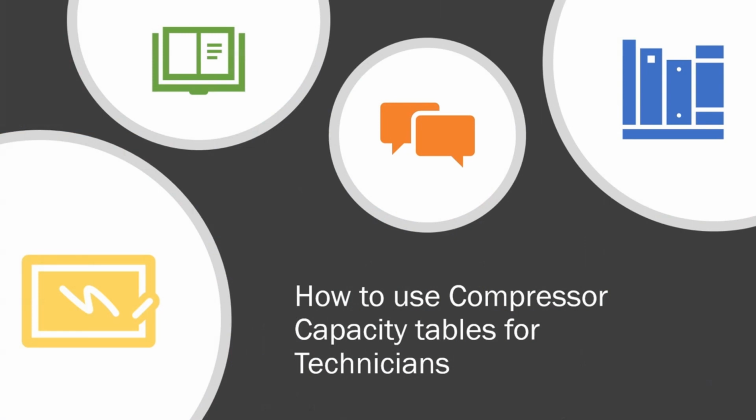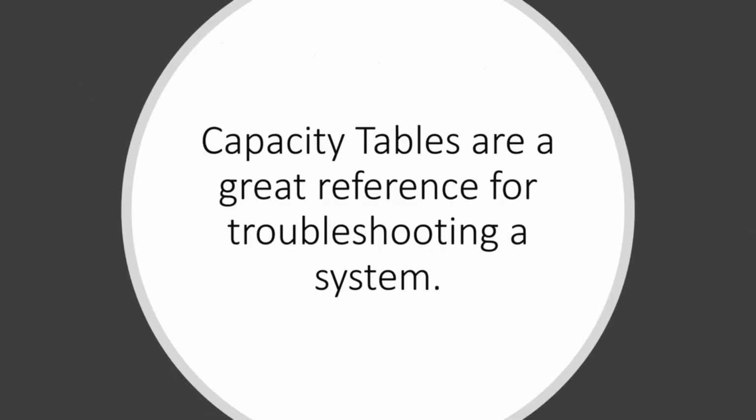All compressor manufacturers publish compressor capacity tables for their products. We will be using a Copeland scroll capacity table for our example today. Quick search on the internet and we can access the data that we need to perform advanced troubleshooting.